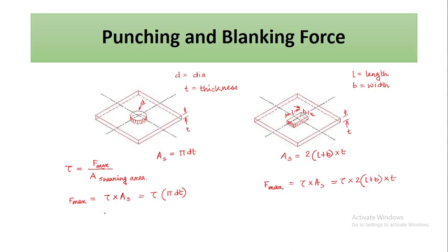than the maximum force required for punching. Therefore, we can write that the punch capacity must be greater than the maximum force required to shear. Okay, so we can write that punch capacity must be F max into some amount.